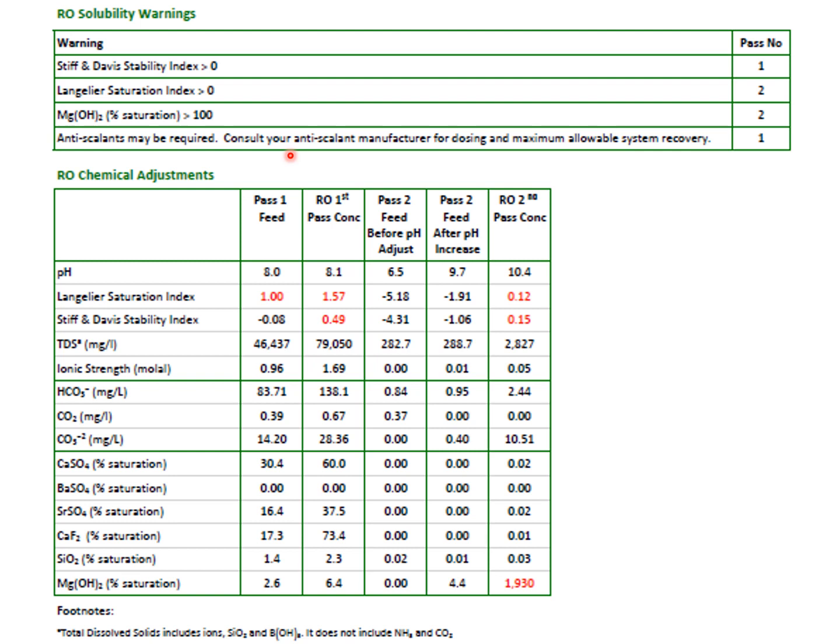So there are several options: whether we increase the concentration of anti-scalant, or decrease the pH, or we can just reduce the water permeability, and the recovery can be reduced to avoid this inorganic scaling impact.